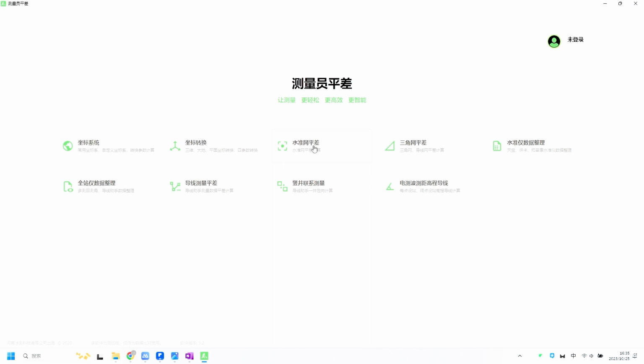After exporting, we can come to our leveling network adjustment interface. On this interface, this requires logging in. In the leveling network adjustment interface, we can create a new project. If the elevation is known, we can import it directly. The file in our control point can also be inputted directly. For example, our first point is designed with an elevation of 100, which is our control point. For our fourth point, it is 102, and in the elevation observation values, we can input it directly.